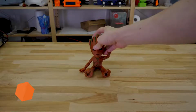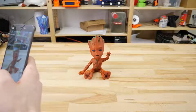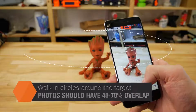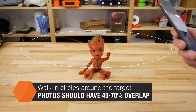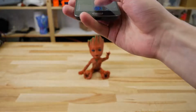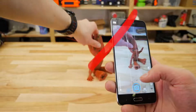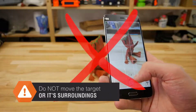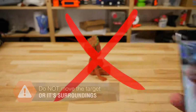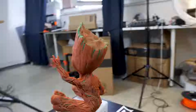Before you start taking pictures, try and light the object evenly from all sides and avoid creating hard shadows. Circle around the object and try to get pictures from as many angles as possible. Don't forget to take pictures from top and bottom as well. Do not move the object or its surroundings between shots. The photogrammetry software is looking for features not only on your object, but also in the background, so this would really confuse it. This is an example of a decent set of photos for photogrammetry.